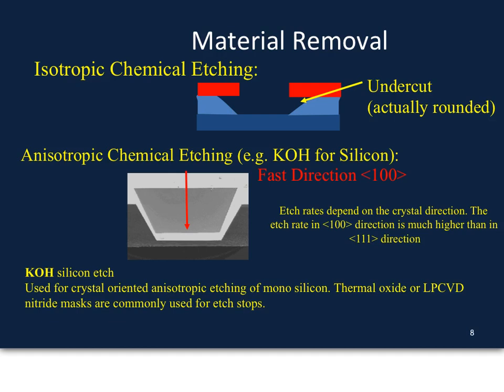would be undesirable. So a lot of effort has been put into developing silicon etching techniques, which can give you anisotropic etches, so that you get a much faster etch in one direction than in the other. So for example, in this case, we're illustrating one. This silicon etch, potassium hydroxide silicon etch, which is a wet etchant, can go 400 times faster in this vertical direction than it will etch in the lateral directions. So the advantage of this, of course, is that we can get much more vertical kinds of walls in our devices.